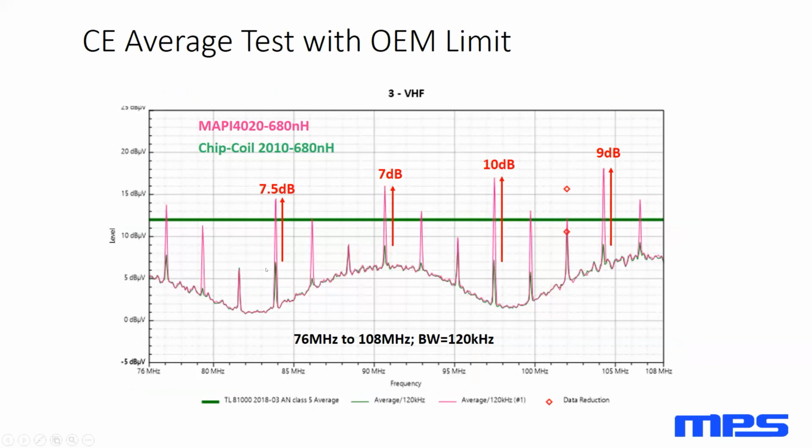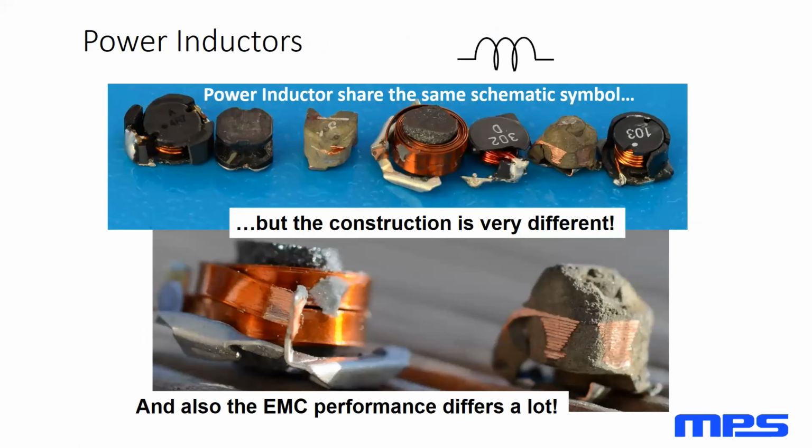So you can see here the limits from the original coil. They're about 7.5 dB higher in some cases, actually 10 dB higher in some cases. And this inductor change is making a significant difference, I'd say mostly from a size perspective. And Francesca touched on it, and we'll go into a little bit more detail about that here.